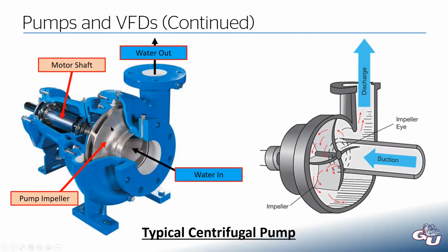So think back to a fan impeller. As this thing spins, it creates an outward pressure that forces water outward, out the top here. And by doing that, creates essentially a vacuum in the center of the impeller, which will then induce some water to draw in. And sort of the same thing over here, just illustrated.